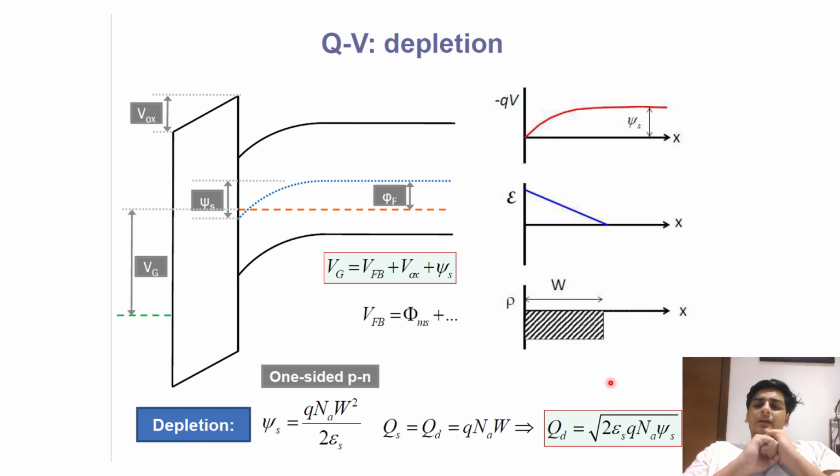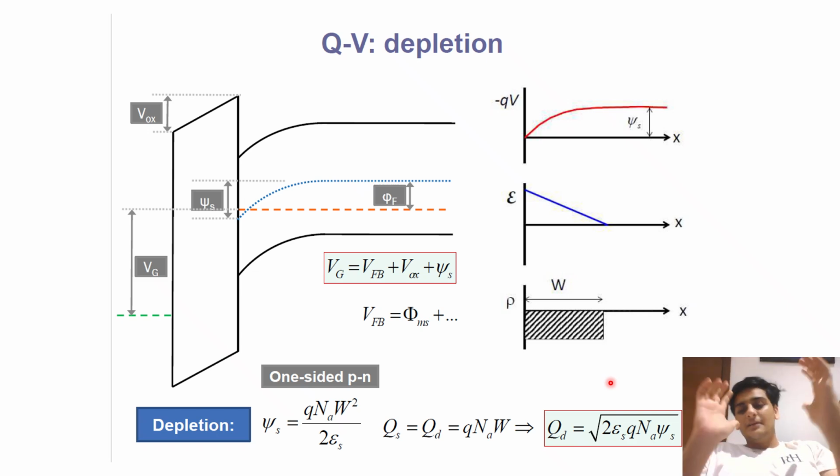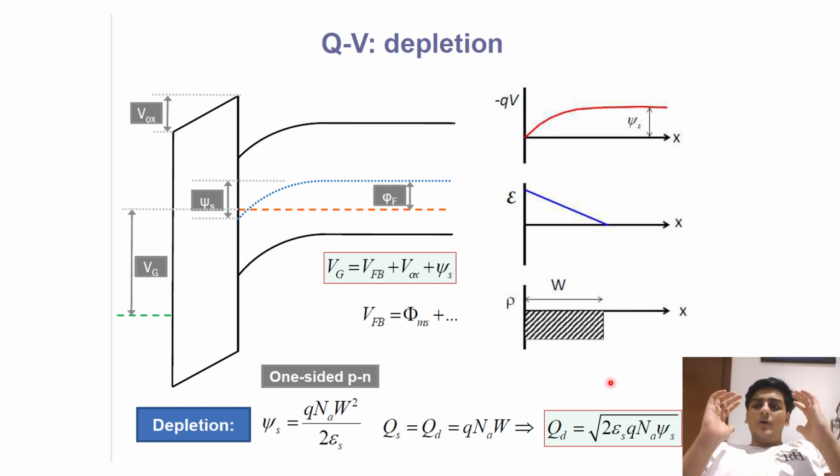Now imagine your N is extremely highly doped. What that's going to mean is that you need very little depletion of the N region to deplete a lot of the P region and still maintain charge neutrality. So what that means is that when you have a very highly doped NP junction, most of the depletion is going to happen across the P region.